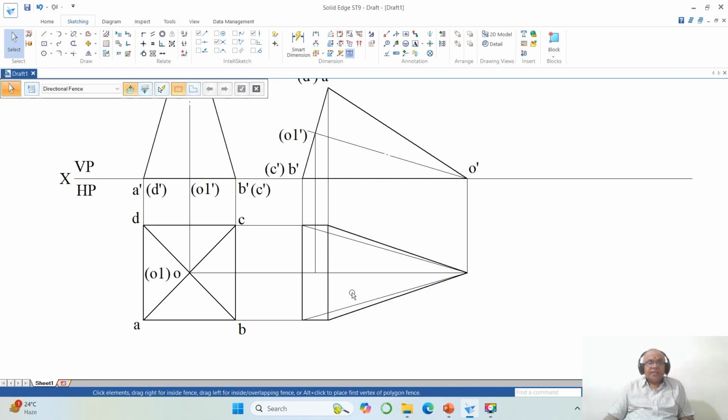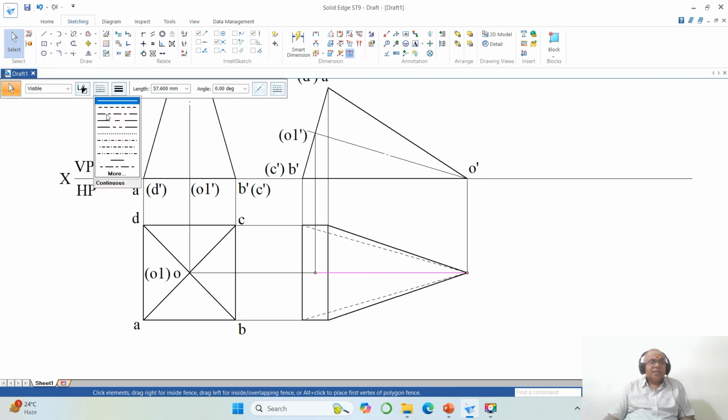Okay. Then the edge or a corner, which is this one and this one. Two visible edges can never cross each other. So you take a hidden edge. Okay, and make it 0.35. Okay. Now you come down to this line and you make this as the axis line.